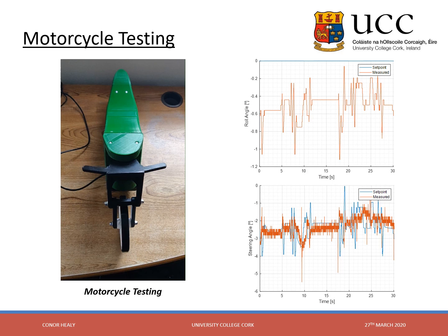Both output plots show deviations from their set points. This is mainly due to a deadband and backlash in the steering gearbox, as well as the lack of a free integrator in the roll control system.